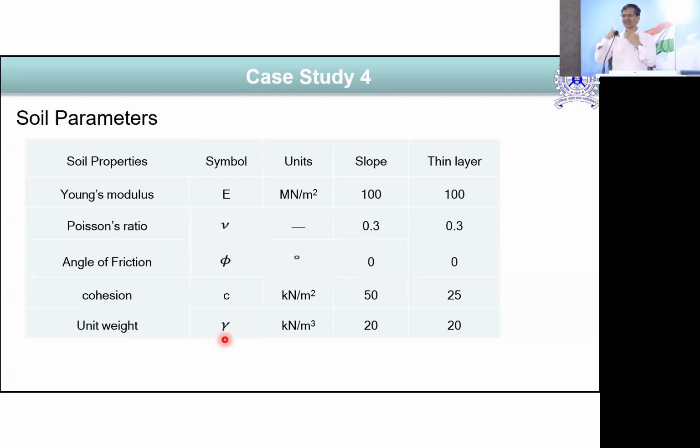Hey, where do we know the soil's modulus? Meaning most of the time we are not aware of it. Soil also can have a modulus. But if you are going for Plaxis, you need to put this in. So that's why I said parameter. The software will ask for this parameter, you have to give it. So you have to see how to find out these parameters.